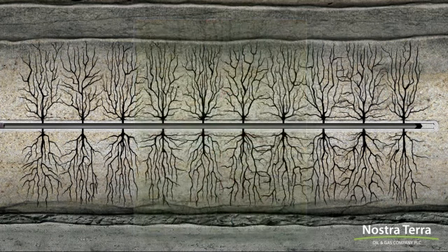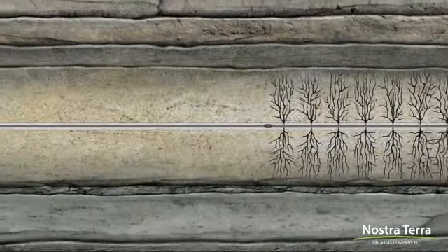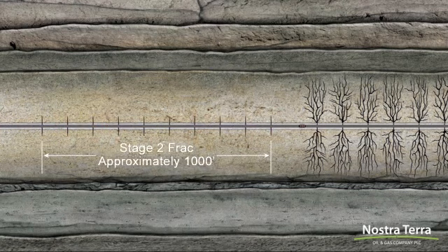wellbore. Next, a temporary plug is placed at the heel or left side of the first stage frac. The plug closes off or isolates the perforated and fracked section of the wellbore so that the second stage section of the horizontal leg can be perforated and fracked.